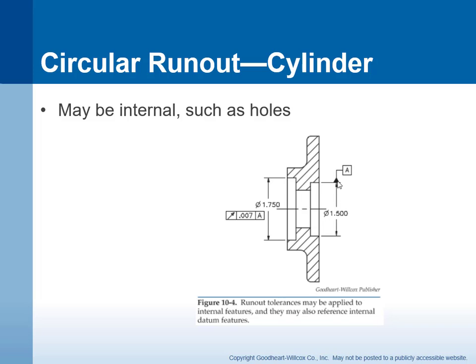In this case, our datum axis is going to be established by this counterbore feature right here. We're going to spin the part and check the runout of these circular elements inside this hole right here.